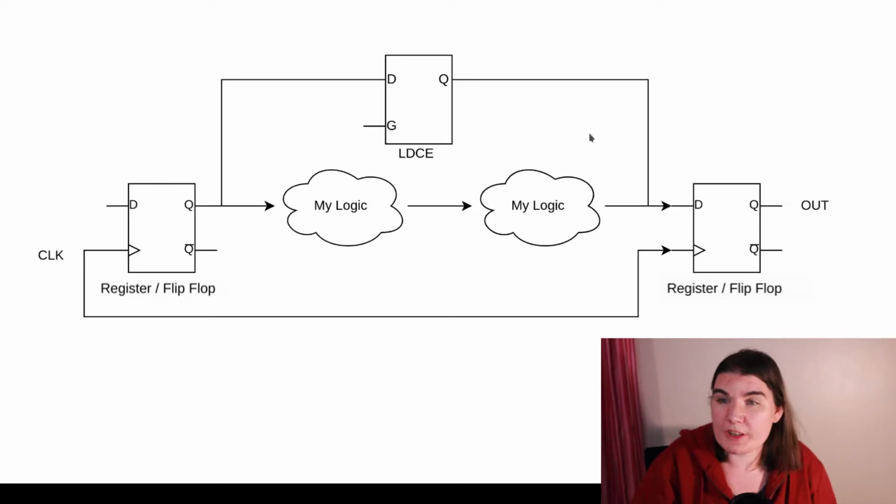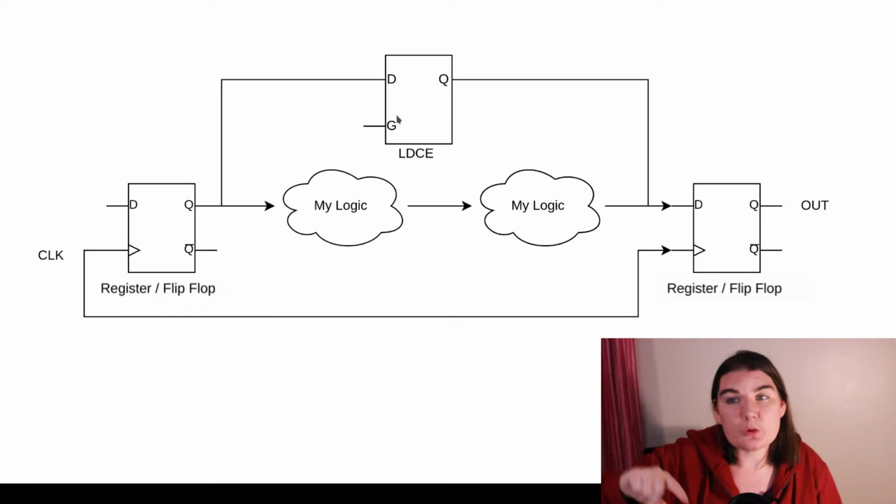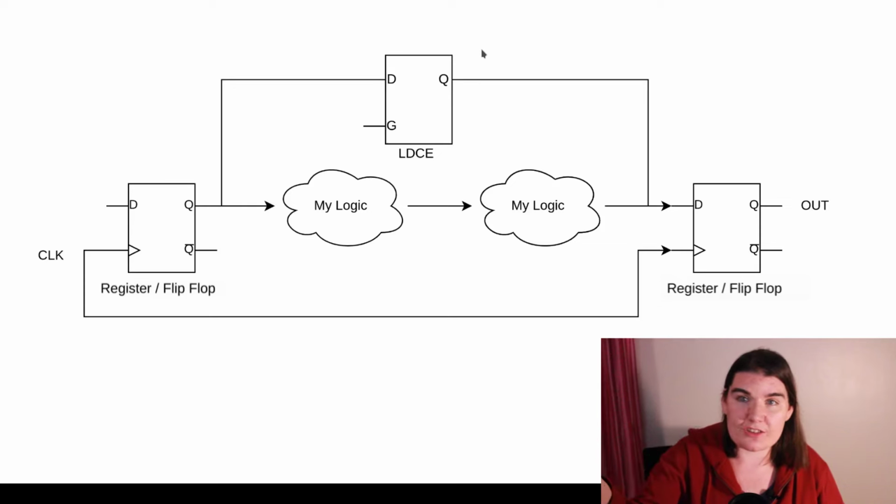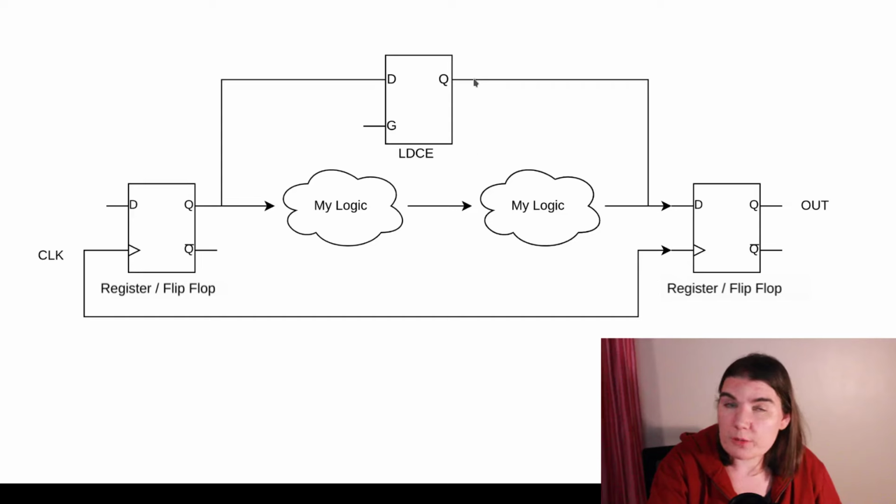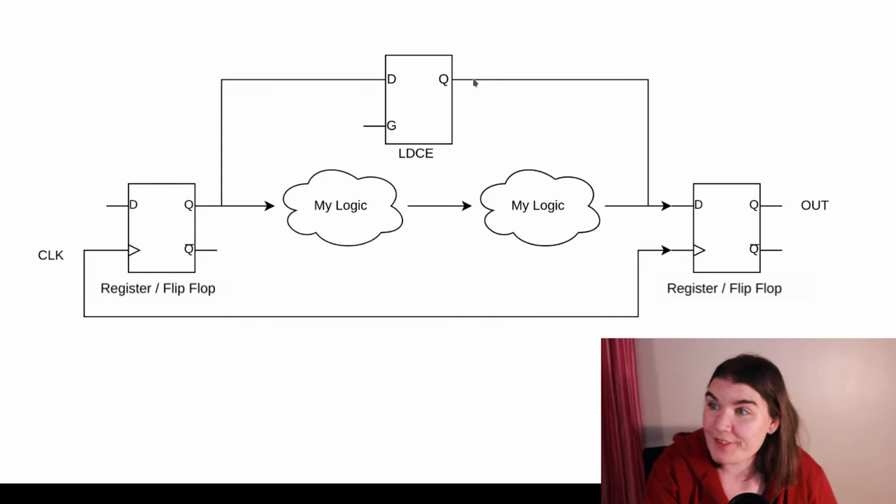But it can't do its job properly because it doesn't have a clock. And it can't give it a clock. The tool can't put a clocked element here because I have to tell it what clock to use. As the designer, I have to say you must use this clock. And so the tool doesn't have enough information to put a proper register here. And if it did, it would also change the behavior of the signal, because then this would be delayed. Remember, the output of a register is for the following clock cycle. And so that will also change the behavior of the signal.